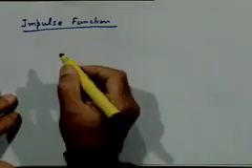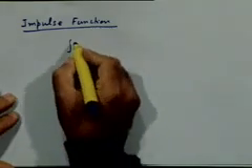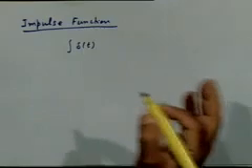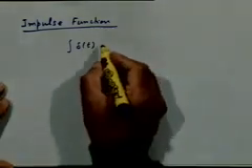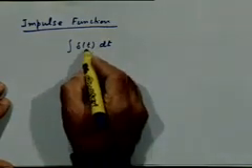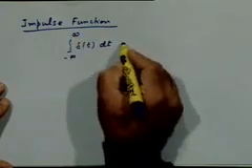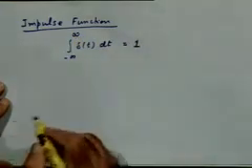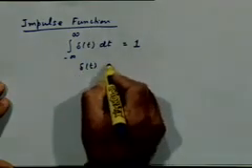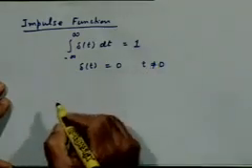There are two ways of defining the impulse function. Well, several ways, not just two. Since this is a review, I will not go into a very detailed description of all those various methods. All we will say is that an impulse located at t equal to 0 is denoted by delta t and is defined to be a function which encloses a unit area under it, and it is 0 everywhere other than t equal to 0.